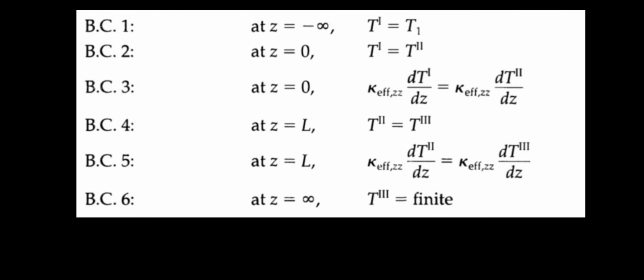flat, indicating that there is no further net heat transfer in the axial direction. This often occurs when the fluid has reached thermal equilibrium with its surroundings or when axial conduction becomes negligible compared to the bulk flow of heat. This is a type of zero gradient boundary condition.